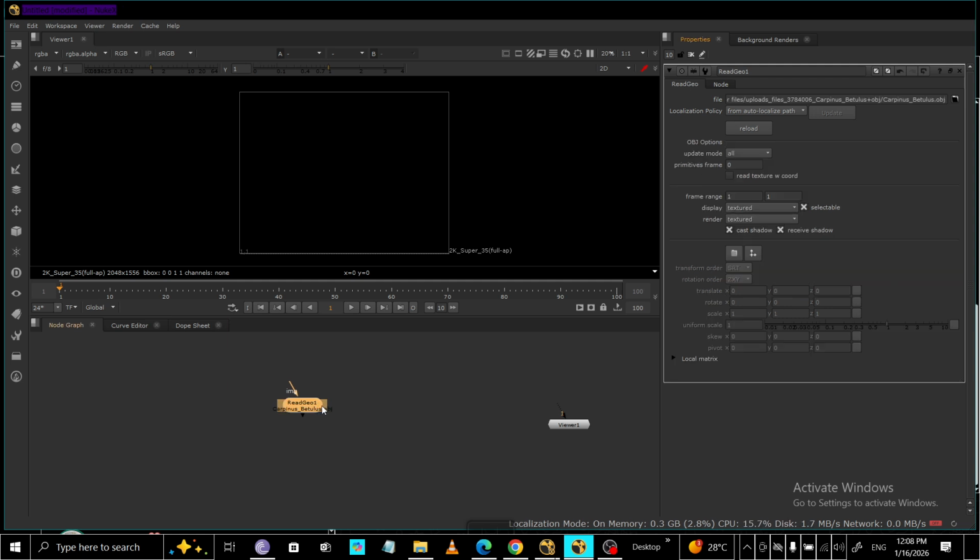A quick tip here, keep your geometry in a project relative folder so the path stays valid if you move the project between machines. If your model looks unusually large or tiny once rendered, that's often due to differences in unit scale between applications, so make a mental note to check scale settings later if needed.